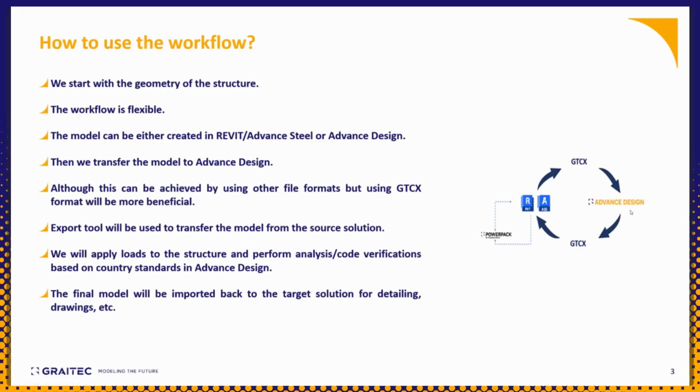Normally we start with the geometry of a structure. You can start the geometry from either Revit or even Advanced Design, and the workflow is fully flexible. You can either start from here through GTCX, send your model to Advanced Design and perform your analysis. Or if the engineer wants to start the model directly inside Advanced Design, it has its own UI to create your model. So you can create your model, perform your analysis,